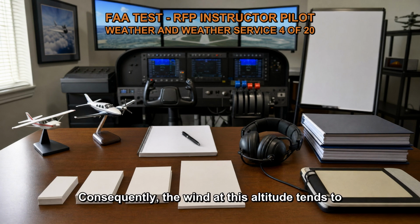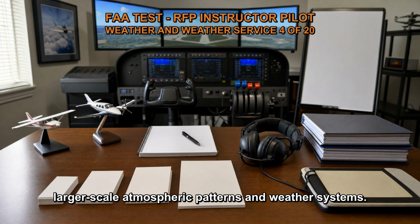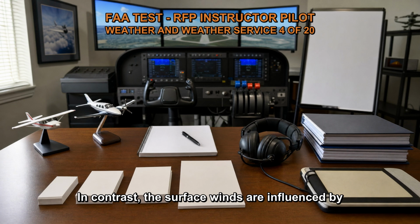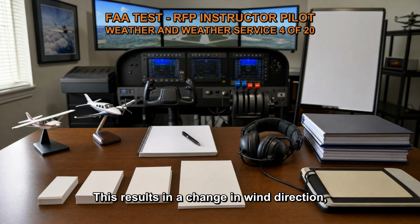At 5,000 feet AGL, the wind is generally less affected by surface friction and encounters fewer obstacles. Consequently, the wind at this altitude tends to have a more consistent direction, often reflecting the larger-scale atmospheric patterns and weather systems. In contrast, the surface winds are influenced by the frictional drag and encounter a greater number of obstacles. This results in a change in wind direction, which can vary from the wind direction at higher altitudes.